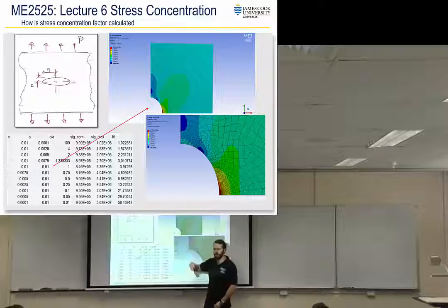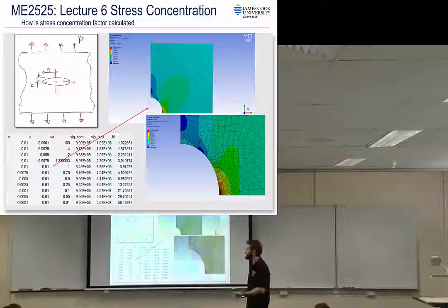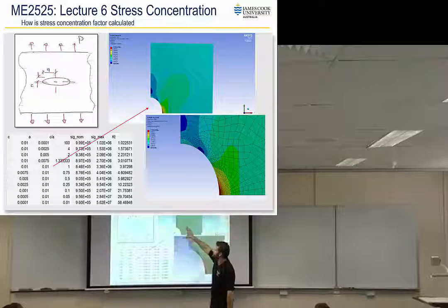So let's think about this. That's a circle, and that circular hole is causing a stress concentration of about 4. So your stress at the tip of that hole is 4 times what it would have been if it was just a perfectly rectangular cross section. It's quite a lot of stress. And so that's quite important in your calculation. Now let's look at some of the different options.